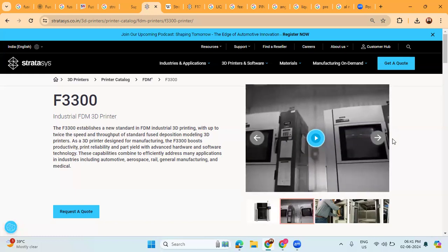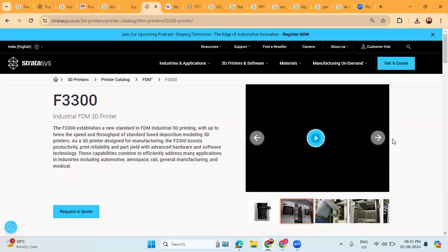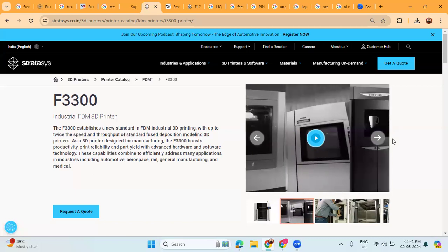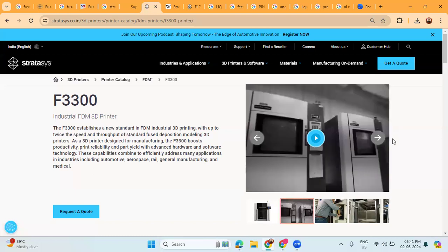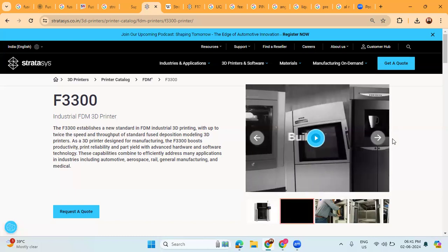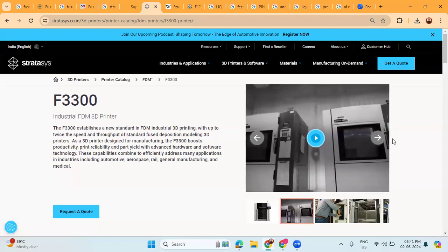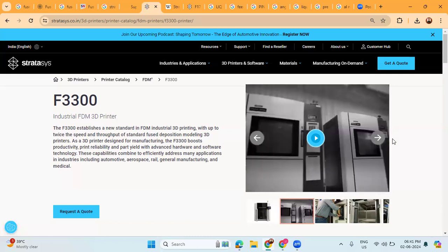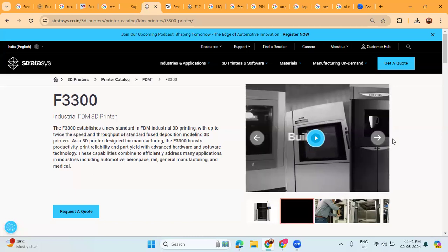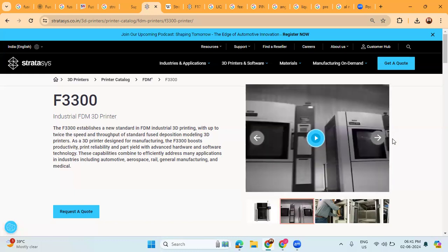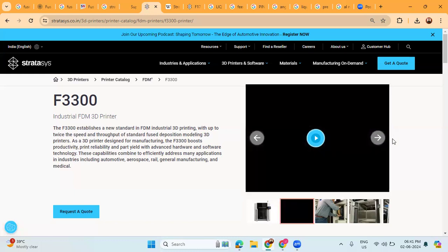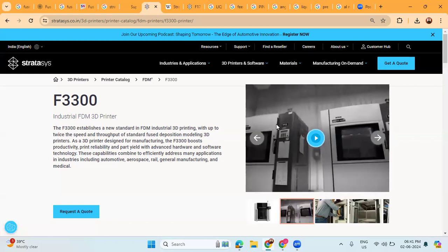The auto calibration feature eliminates the time previously needed for manual calibration after a material change. Multi-resolution printing uses small and large bead thickness in the same print job to expedite the time required to complete the part. Faster extrusion rates enabled by new extruder technology contribute to faster print speeds and greater throughput.